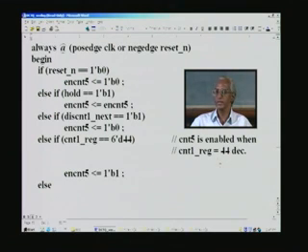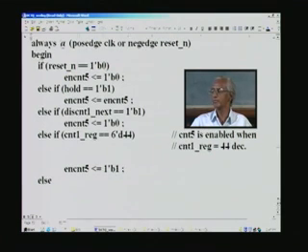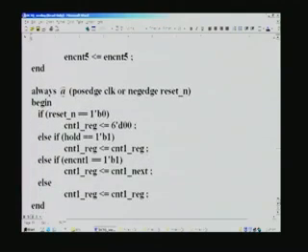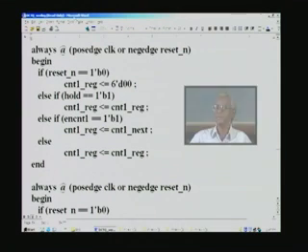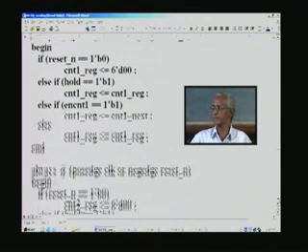And exactly the same thing which we have seen before: you have seen in the architecture that we had 45 clock cycles delay in total, and this counter starting from 0, 1, 2, 3, up to 44 is exactly 45, and this explains why 45 pipeline stages were there. And this one is for the actual counter. The counter is also exactly similar to enable, except that when the counter is enabled it will be incremented. So, counter 1 next was actually counter 1 reg plus 1, pre-incremented, which we have seen before, that we assign only when the counter 1 is enabled, and similarly for all other counters here.